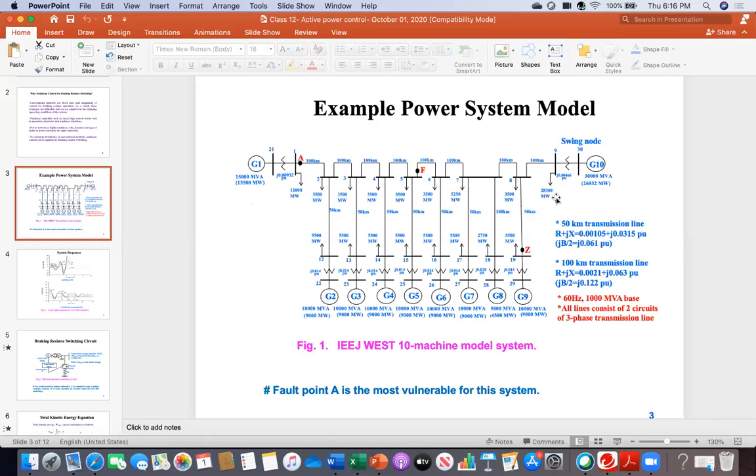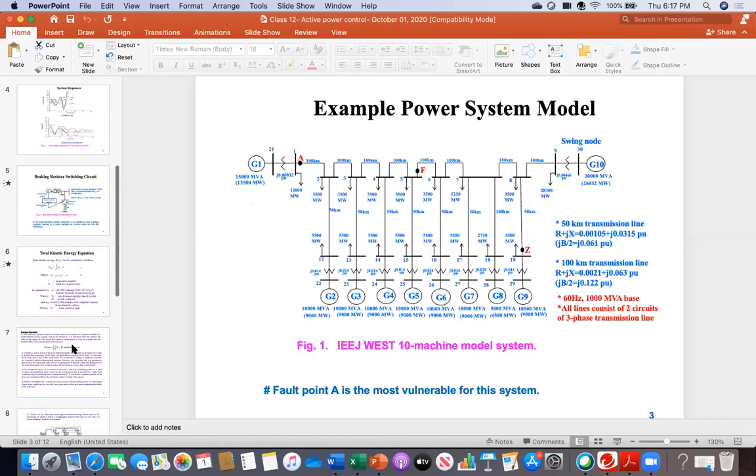It may happen for any of the generators. There is a generator, you want to connect another generator at this point. So what is that condition? What will you check? The synchronism. Synchronism, right. For example, as I said, if it has 11 kV or 13 kV, then the generator that you want to connect should also have the same voltage. There should not be any voltage difference.